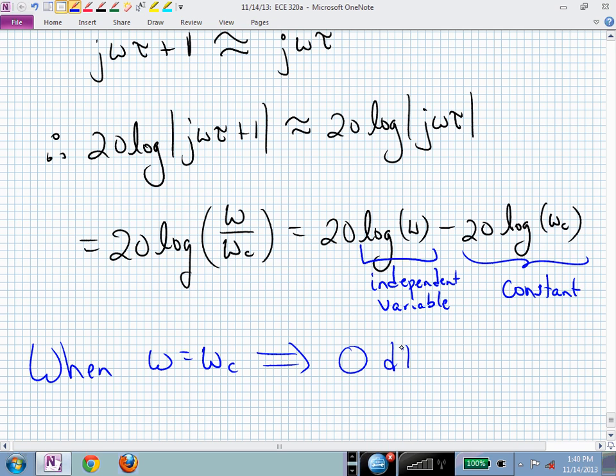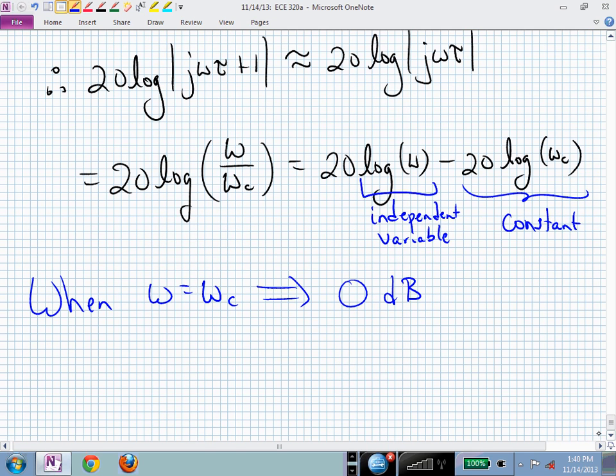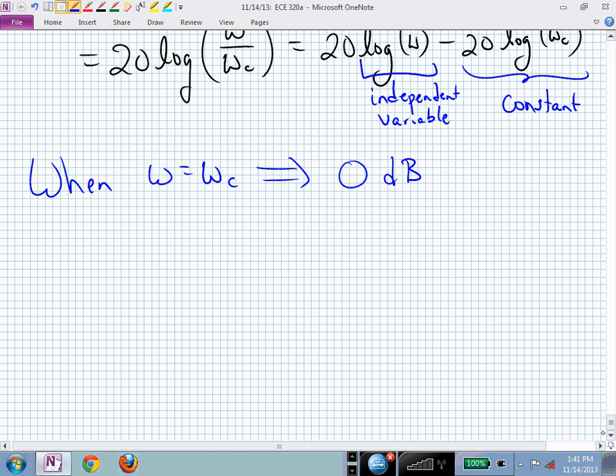So now we have intersected the two extremes right at the break frequency. So we were flat, then we were sloping, and they meet right in the middle at the break frequency. But this now, in terms of what we now have, the magnitude is equal to 20x plus b.